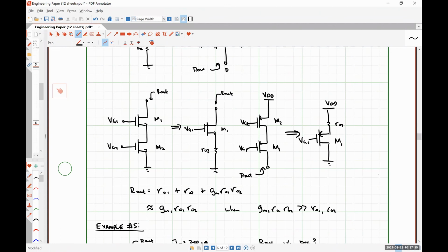So if we tie V_G1 and V_G2 together, the source for this transistor M2 is down here, but the source for transistor M1 is up here. It would force this guy into cutoff, so it wouldn't work correctly. So these are actually two different voltages. And typically speaking, this guy is V_GS plus 1 overdrive voltage, meaning we're biased just far enough into the saturation region to where it can amplify our signal. And then this guy right here is that same V_GS plus 2 overdrive voltages, which pushes it up enough to be operating in saturation.